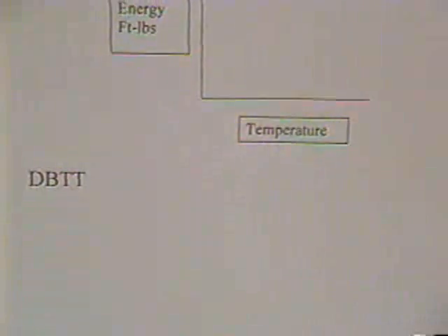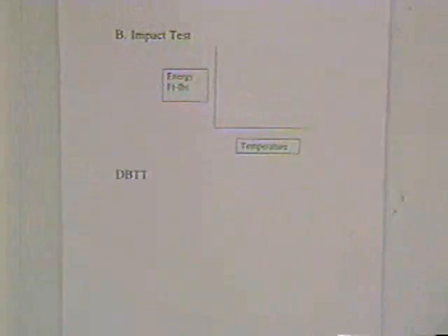Now, another mechanical property that is important is the measure of how a material behaves under impact load. The tensile test is a real good measure of the behavior of a material under a static load. The sinking of the Titanic is a nice example of materials that were strong enough and had sufficient ductility. They didn't know enough to evaluate them for their impact characteristics. And once it crashed into that iceberg, the material behaved in a brittle fashion, so a number of cracks opened, not the 300-foot gash that was first originally thought.